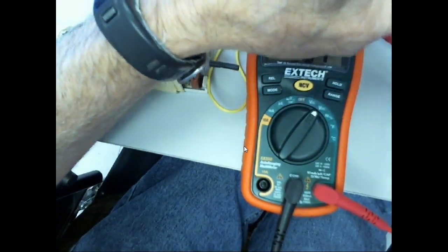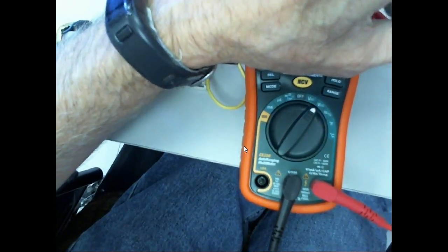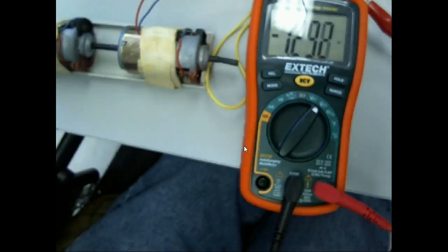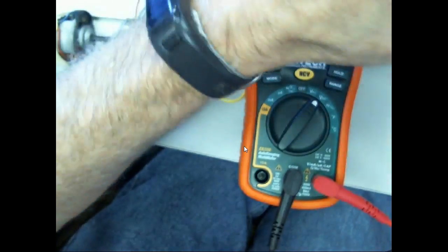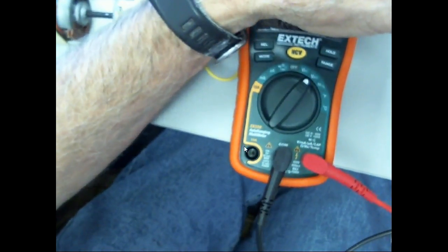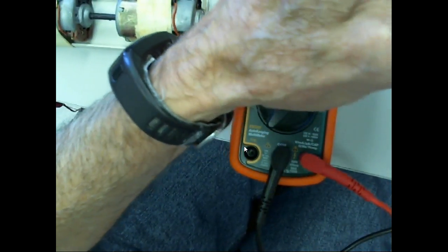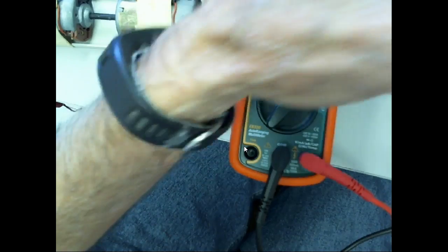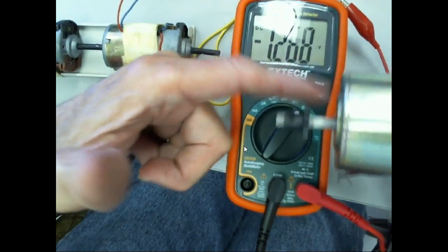There's 6 back here. But this guy has got to turn 65.5 times to make this guy over here turn what? Once. So this guy sees this 6 times 65.5. And that's what you got to know. You got to know what this sees the encoder as, not what the encoder is right there. Because this is where we're trying to set the speed at, right? You understand? This is the output shaft right here.